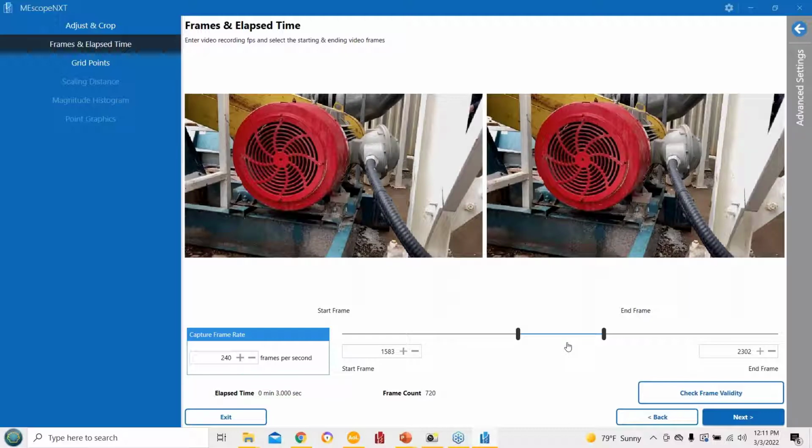The longer you take it, if I took 10 seconds, it's going to take longer to process the data, but you're going to get better averaging. If you're doing the ODS FRF calculations, you'll get much better averaging and noise floor reduction. So it depends on what you're doing. If you're just looking at the video, 3 seconds is plenty to see the shapes and how it's moving. If you're going to do some signal processing, then a longer frame of reference might be required, okay?